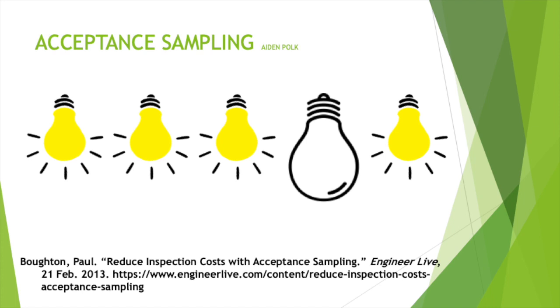Suppose you're a quality engineer working for a company that sells light bulbs. You may communicate with the manufacturer and conclude that you will sample 50 light bulbs out of a lot of 1,000, and if 2 or less are defective, then you will accept the lot. Light bulbs are easy to return and replace if a customer receives a defective one, so you may decide that you would rather not scrap an entire lot for that small of a number of defective units, which could cause you to decide on a new acceptance number of 5 out of 50.